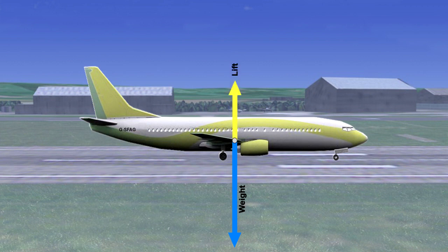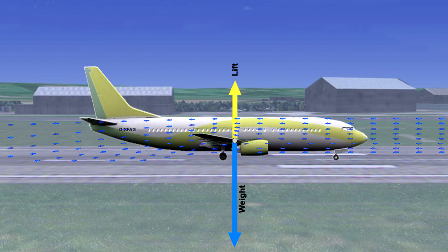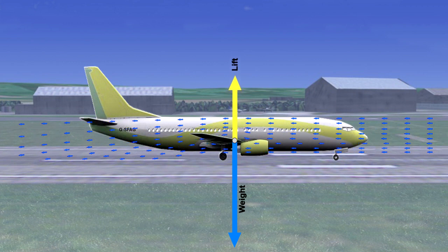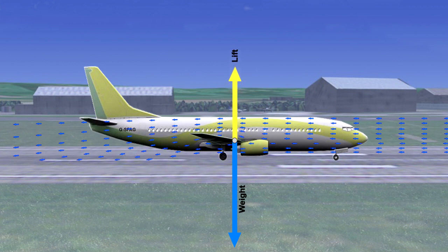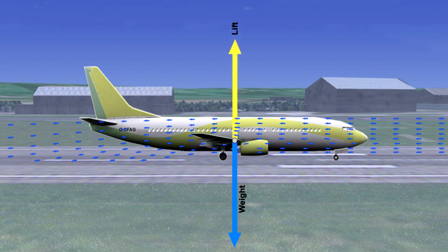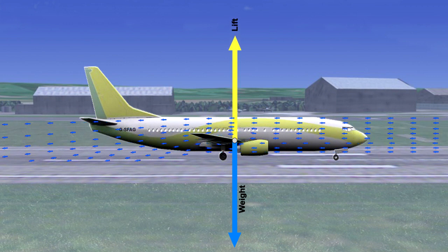In simple terms, to generate a lift force, we need a mass of air to pass over an aerofoil. The aerofoil in our case is the aeroplane wing. To make the air flow over the wings, the aeroplane must be pushed through the air. The faster the aeroplane travels through the air, the more lift will be created. The aim at takeoff is to gain a sufficient amount of forward speed to create enough lift to help counteract the weight, and thus allow the aeroplane to fly.